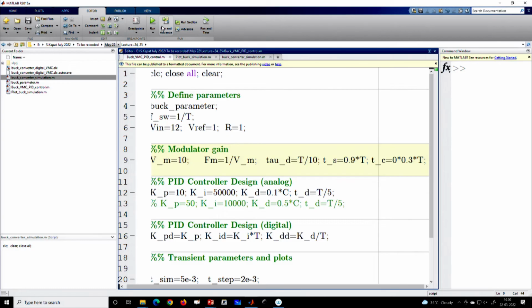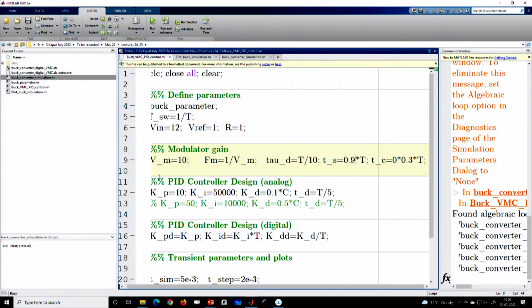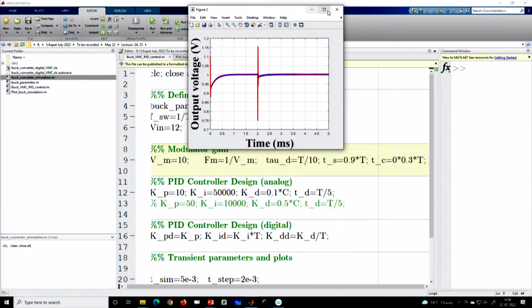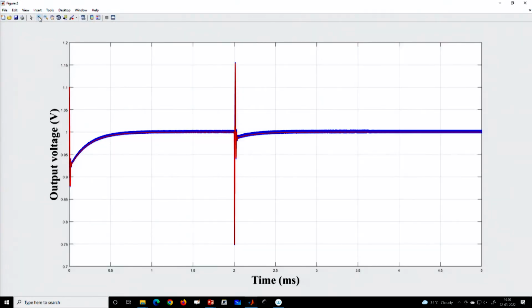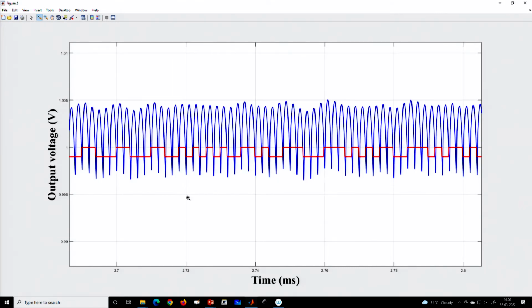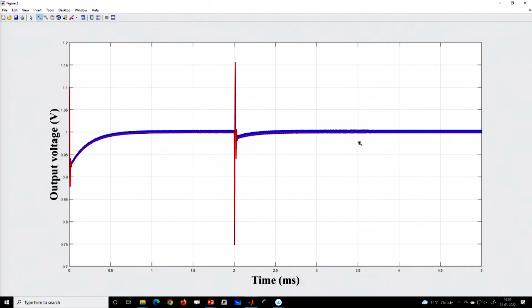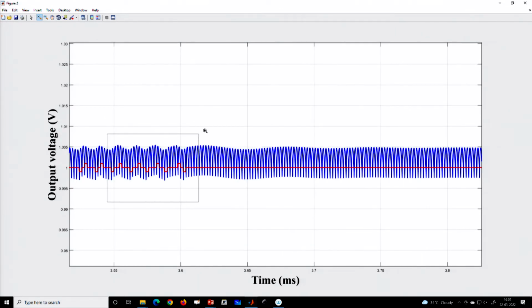Now if you reduce this quantization level, let us say to 1 millivolt, then you can actually improve this response. That means you can somewhat improve the stability status. So you can see now the effect is substantially reduced. It is there, but it is substantially reduced. In the steady state also, only after a long time is this effect gone.